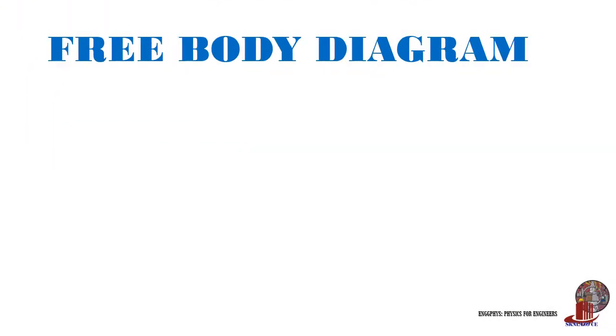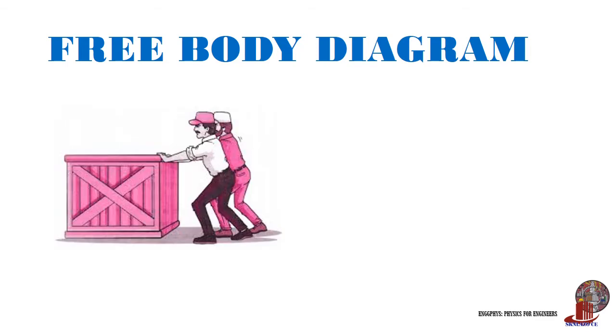The FBD, or free body diagram, is a graphical representation whereby the object of interest is transformed into a particle no matter its size. The forces are reflected in the diagram to clearly annotate the required. For the example of a crate pushed with a certain force, the obvious forces to be considered are the weight, directed vertically downwards, and the applied force as shown. Unseen reactions are the normal force, which is the reaction of the surface to the weight of the crate, and the frictional force, which is the reaction of the surface to the applied force.